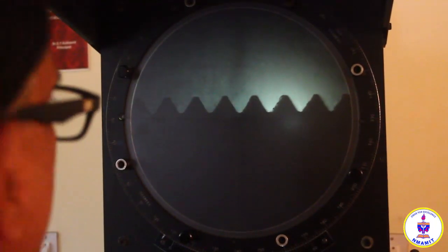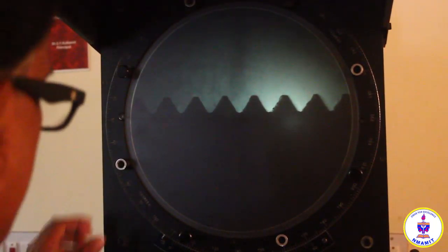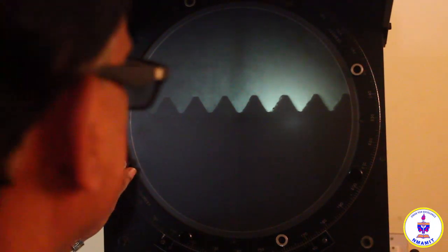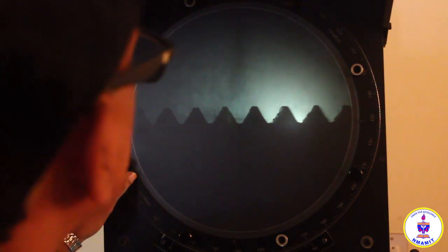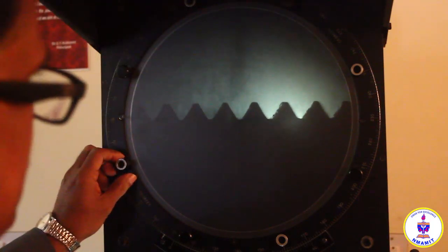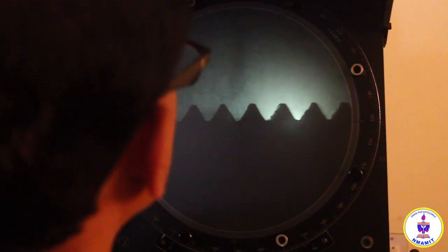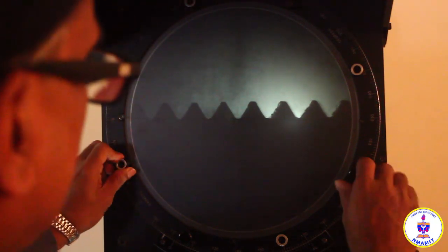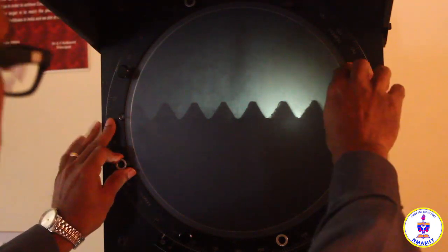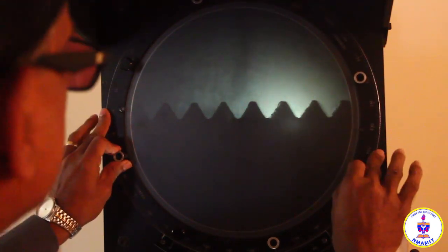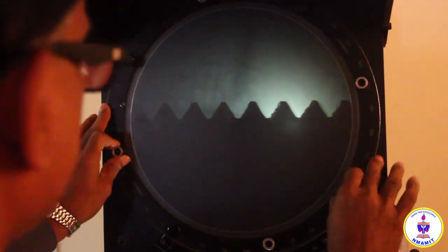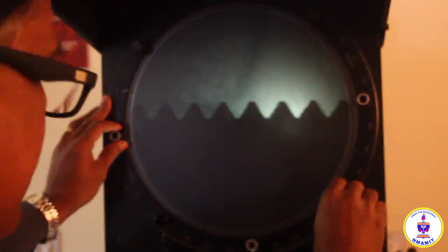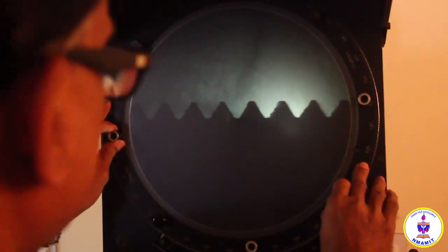Now to measure the flank angle of the screw thread, flank angle is half the thread angle. So we can measure the thread angle here. For that, you choose one of the cross lines here. Let the vertical cross line be at the root of one thread here. Now this scale has this ground screen. This has a protractor engraved in degrees. So the angle measurement can be made on that.